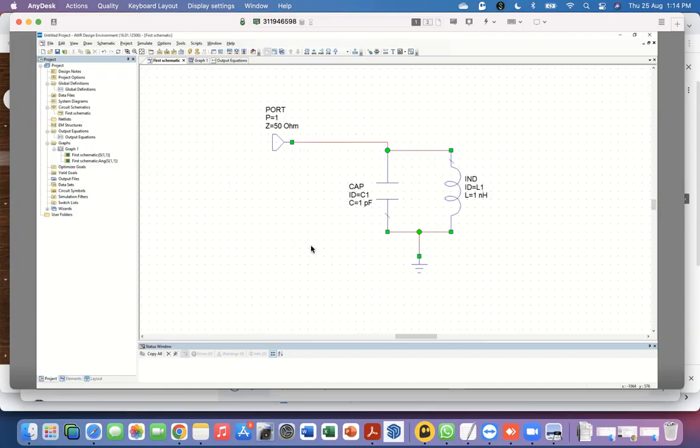You will measure the voltage across a component, or you will measure a current through a component as a function of frequency. And you're absolutely right that in such a case, you will see some kind of a peak or maybe a dip. Remember what S11 means, right? We will, of course, define these quantities in more precise ways earlier on. But S11 is a scattering parameter. It only talks about reflection of waves or transmission of waves.